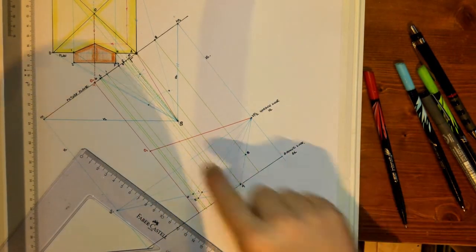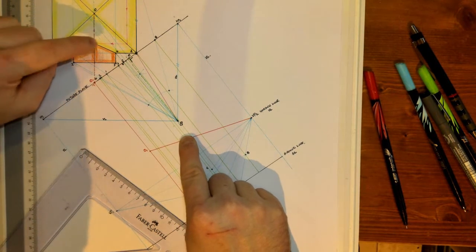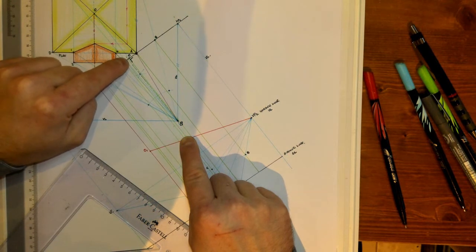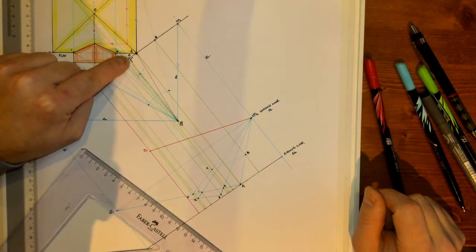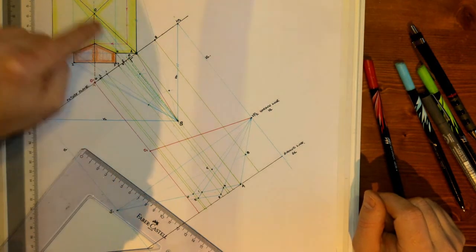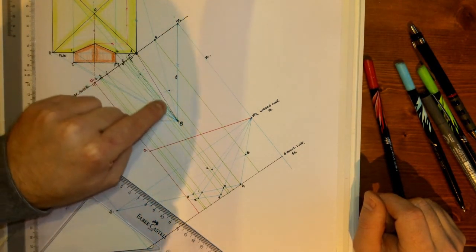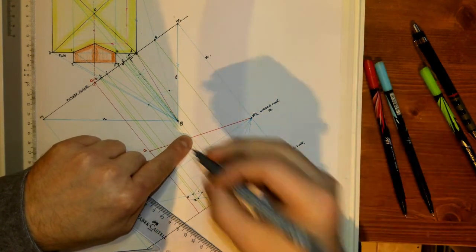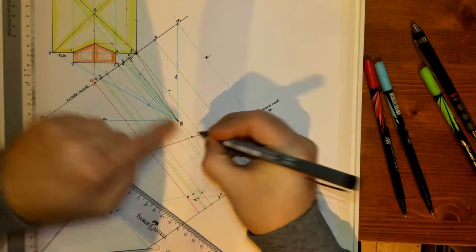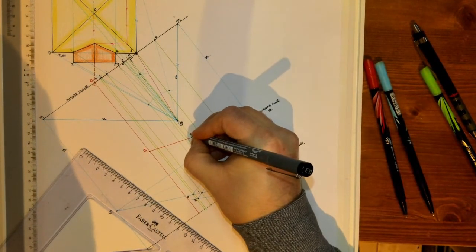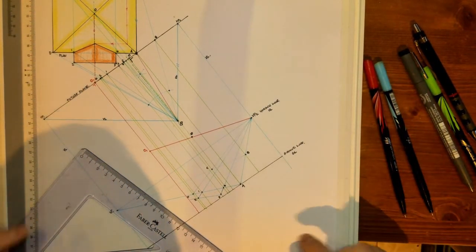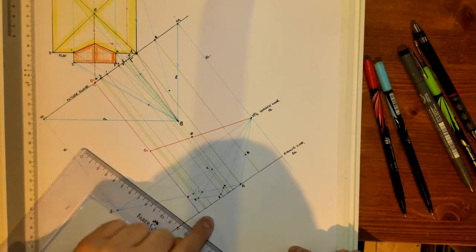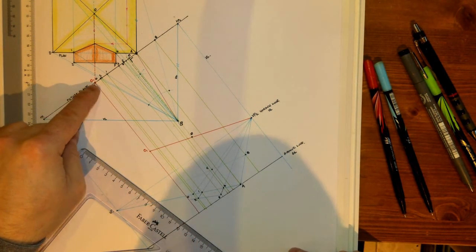What do we want to do with that? Where that red line intersects the point O that's to be brought down, okay, and we have it brought. So there's O on the picture plane, the original O, after it was brought to point S. Where that line intersects that red line I've just drawn now, that is my top point. So there we go. That there is the real point O found. Okay? So we slid O forward onto the picture plane.